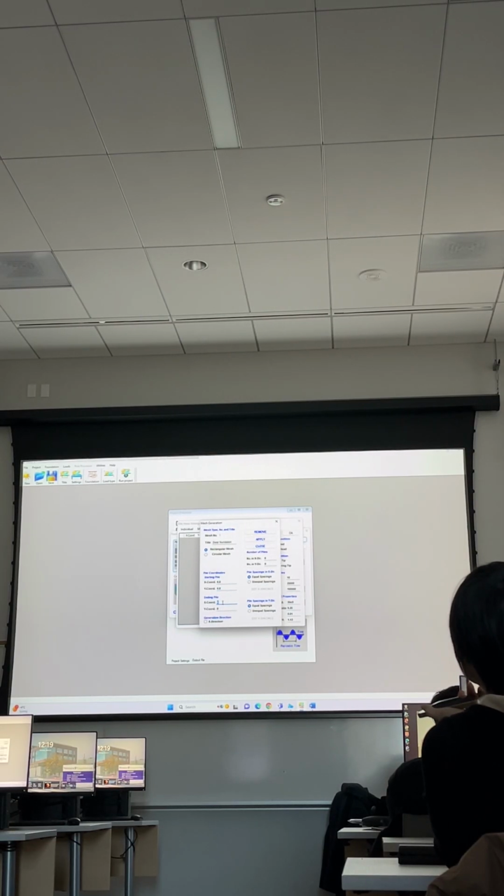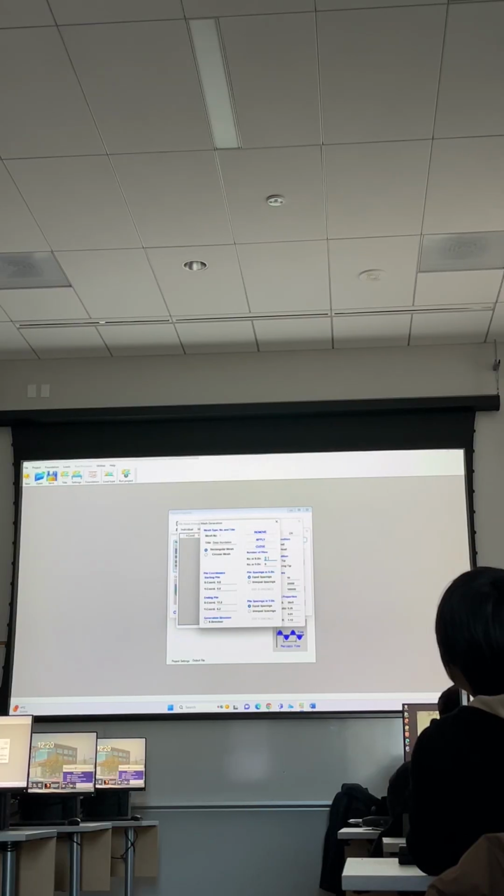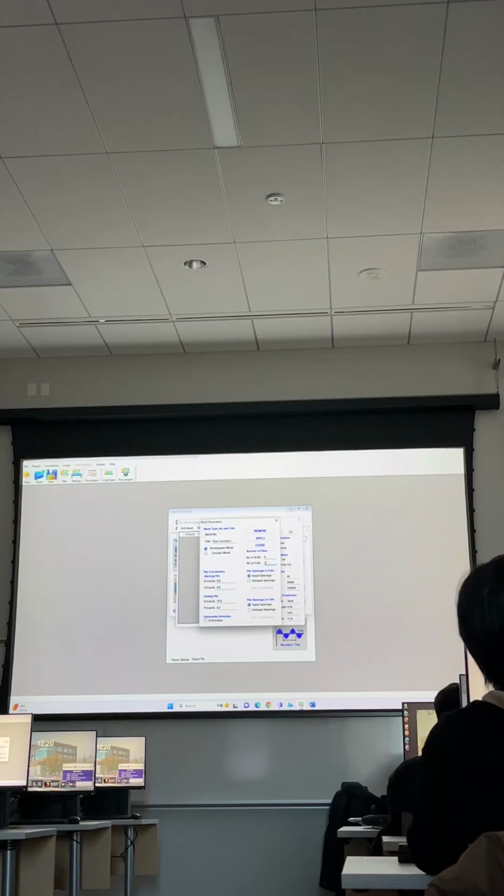The ending one is 13.2, 14 minus 0.8, so it's 15.8, and it's the same here, it's 6.2. And it's equal spacing. The number of piles, I will assume that the number in x direction will be 6, and the number in y direction will be 3. Okay? And it's equal spacing in y direction also. Everything now is okay.